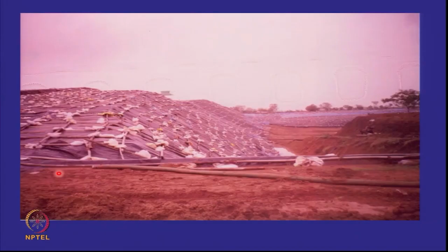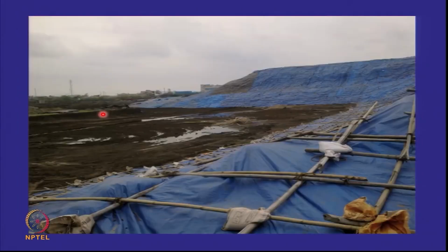This is also another shot which I might have showed you. This was temporary coverage before the monsoons. And this is a big contract. They call a regular contractor who puts all this thin geomembrane, then he puts bamboo, then he puts these sandbags, because when you have gusts of wind, it blows. And this is a hazardous waste landfill. So the more leachate that gets produced, the more money you have to pay to the ETP, and the owner wants to make profit. This is the situation.